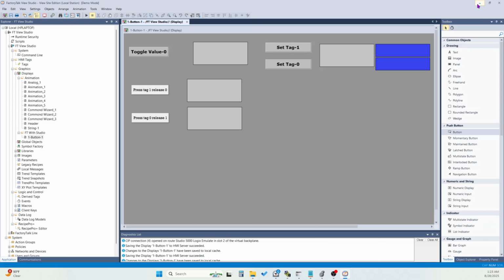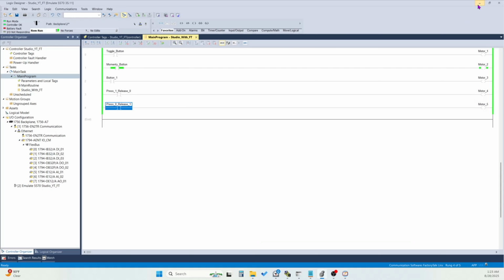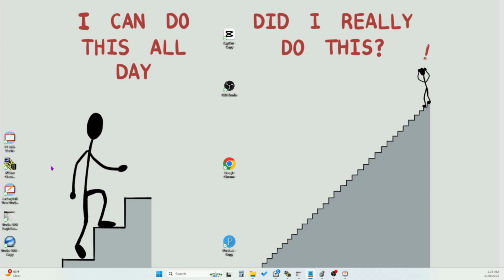I already created the runtime, so I will not create it again. If you created the runtime once, you need not create it again and again. You can use the same runtime, and whenever you change something inside of SCADA, run the runtime and it will reflect automatically. If you are changing some display setting, then you can edit directly. And if you don't know how to create a runtime, you can see my latest video, how to create a runtime in 30 minutes. So double click on runtime.